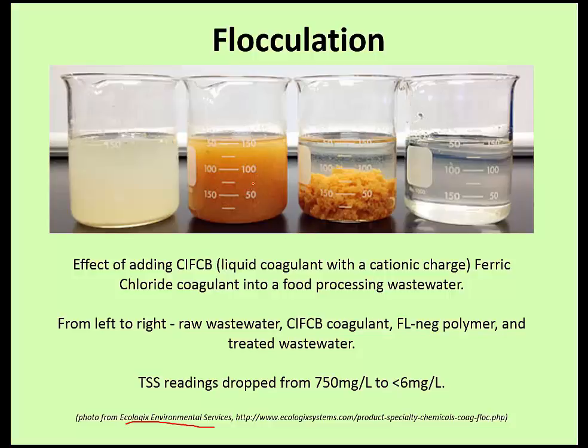You can see that it begins to create this precipitate. It begins to flocculate out. Here we can see that this flocculant polymer, this is the material they've added, has a positive or cationic charge. So now we've got this polymer basically that forms and precipitates out of solution. They can separate it out, and then they have the treated or cleaned wastewater.